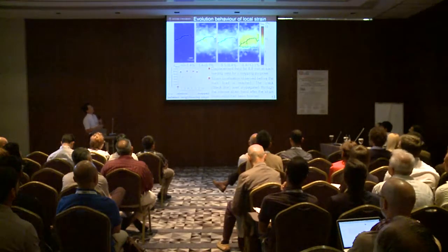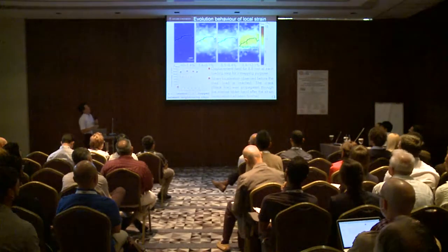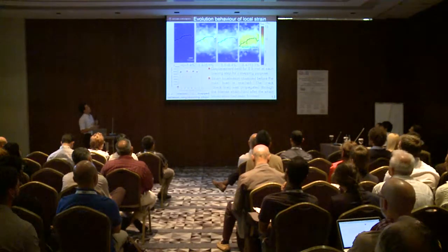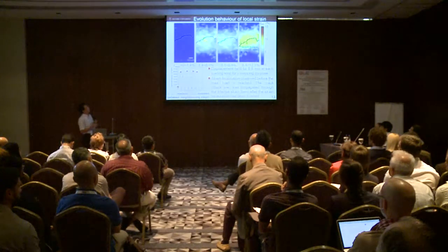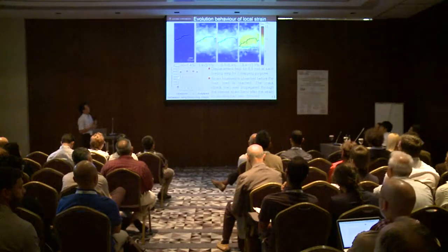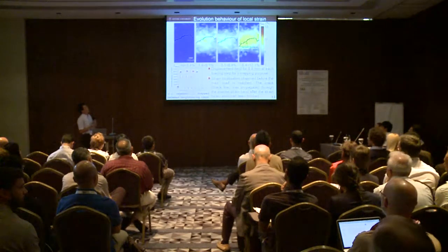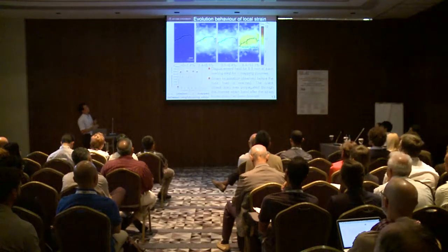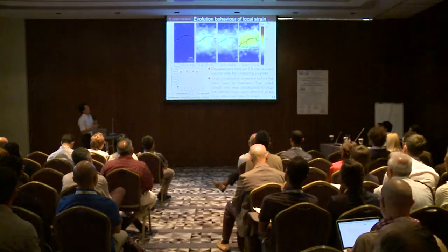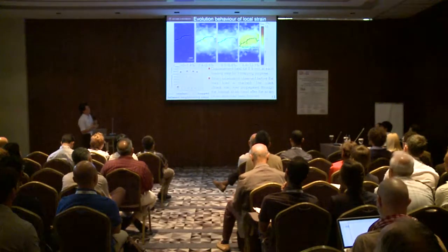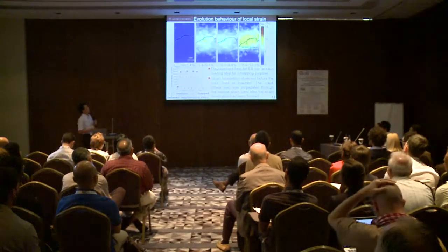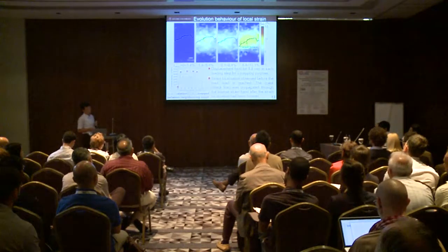So you can see that strain localization was observed even before the maximum load is applied. And also the initial strain localization was observed just after the elastic limit is reached. And then the quasi-cleavage crack was propagated through this intense shear band after the strain localization has been almost finished.